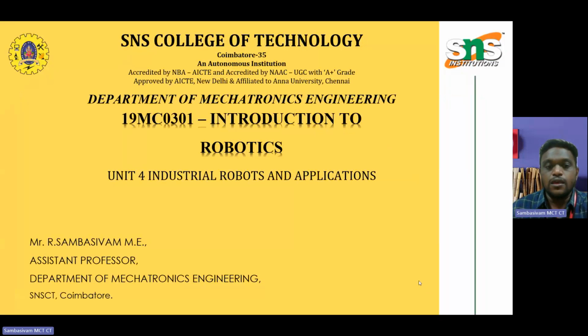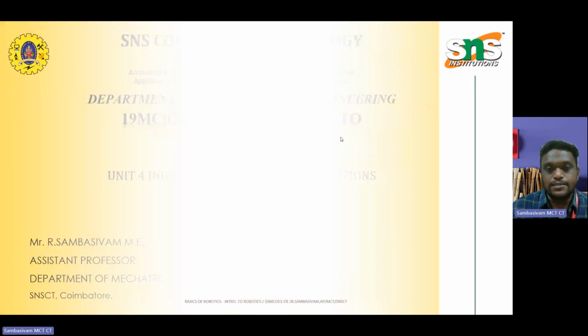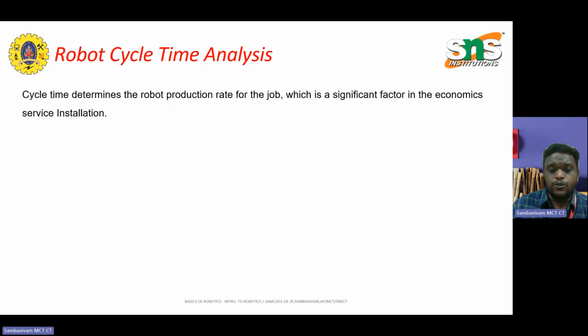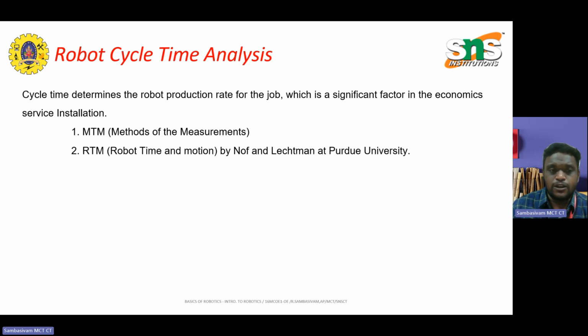The robot cycle time analysis is considered for various robots under their control, based upon factors like the robot model, the controller model, configurations specific to the task you are performing, the speed and acceleration of the robots, and some factors related to subtle differences between the physical robots. As a result, it is not always possible to get a completely accurate cycle time calculation in a robot simulator, but you can get pretty close with the right tool.